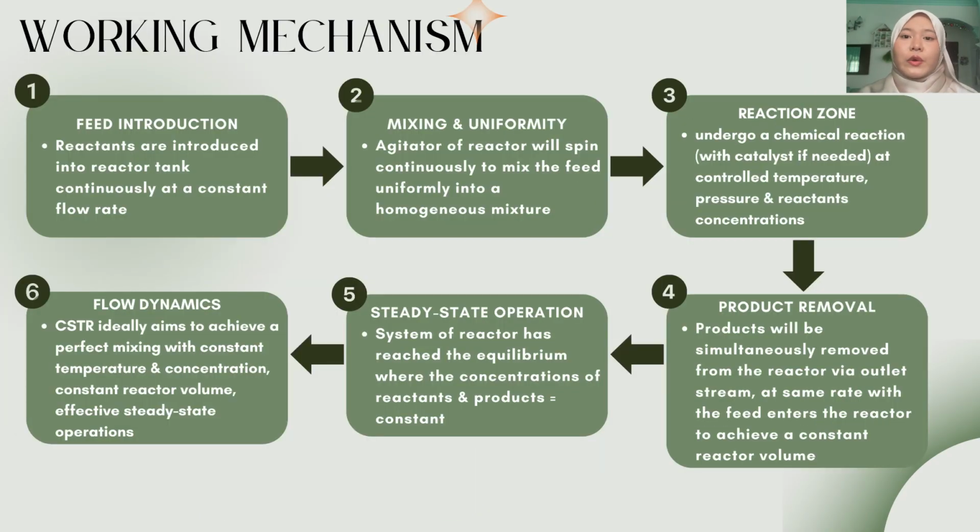So I'm going to talk about the working mechanism of CSTR. Firstly, feed introduction. What is that? Basically, the reactants or the feed will be introduced into the reactor tank continuously at a constant flow rate. After that, the agitator of the reactor will spin continuously to mix the feed uniformly to produce a homogeneous mixture. And thirdly, we have the reaction zone. The feed will undergo the chemical reaction with the exposure of catalyst if required, at a controlled temperature, pressure, and also concentration of the reactants.